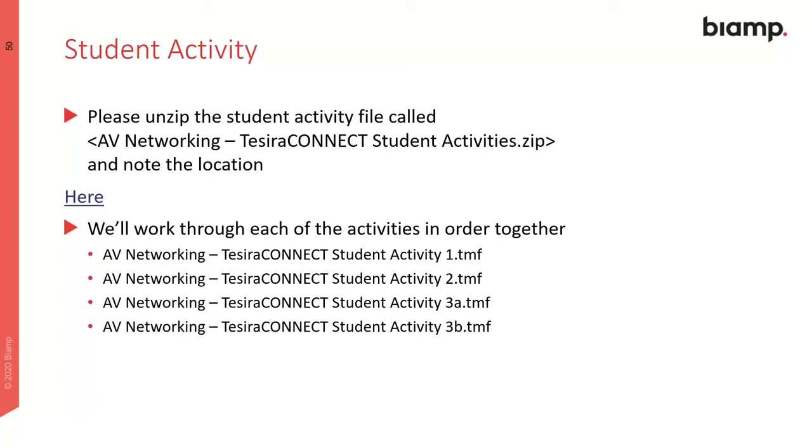Once you add the TC5D, it pretty much fixes how clocking is done within the system. In the case of other systems, there is an option in the software to assign Dante or AVB as the master. I think I'll show you in the Dante Controller what exactly is happening with the clocking.